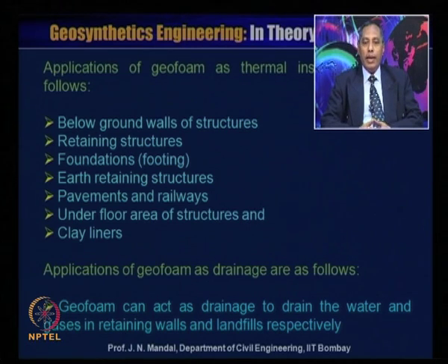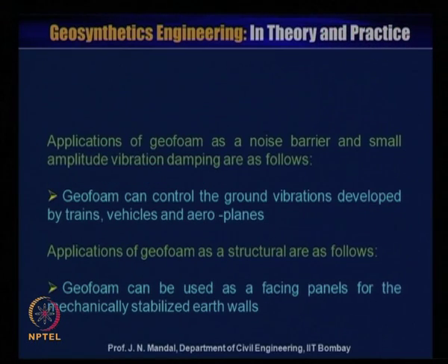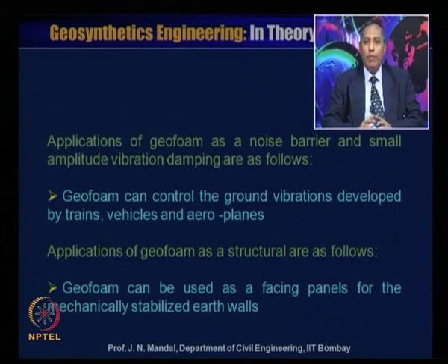Application of geofoam as drainage is as follows: geofoam can act as drainage to drain the water and the gases in retaining wall and landfill respectively. Application of geofoam as a noise barrier and small amplitude vibration damping is as follows. Geofoam can control the ground vibration developed by the train, vehicle and aeroplane.